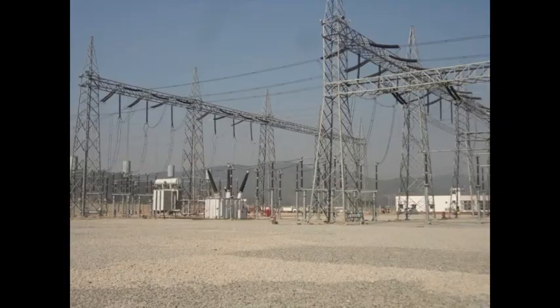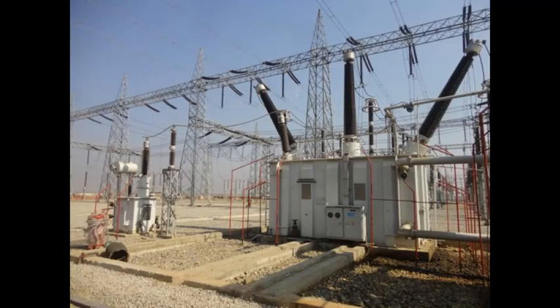Switchyard is the station level layout planning, and it requires a lot of space, and generally it is always preferred to have the switchyard in such a way that it is accessible for all the units for initial power supply as well as generated power evacuation.